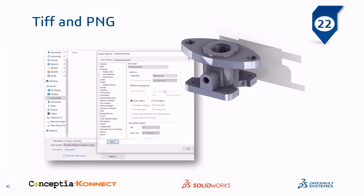An extraordinary hack is you can remove your background and information other than your CAD model by selecting Options under the Save As tab. After you select the format, choose the Remove Background option. Now you can see the CAD model image overlaps the image of system options, which is shown on the screen.